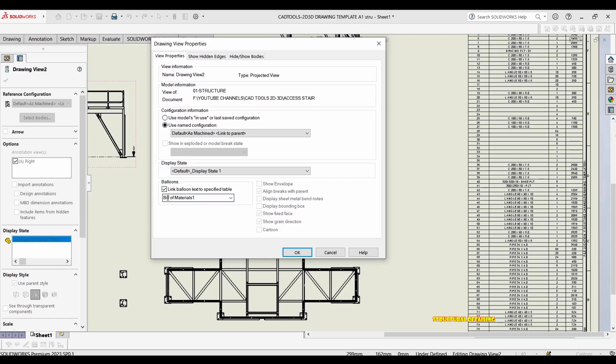But now that we went to indented or fully detailed parts, it still shows you as number 1 because it's still linking it to that previous table and not the current one. So you have to make sure that it's linking it to the current one. Even if you don't have that table anymore, it still sees it as that one because that's what it began with. So you have to come in here and update it and make sure that whatever is in here is linked to the relevant table. That's how you make sure that everything is linked to a relevant table.